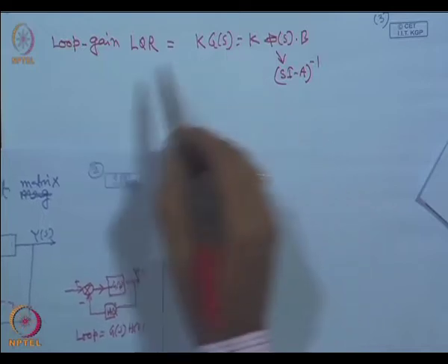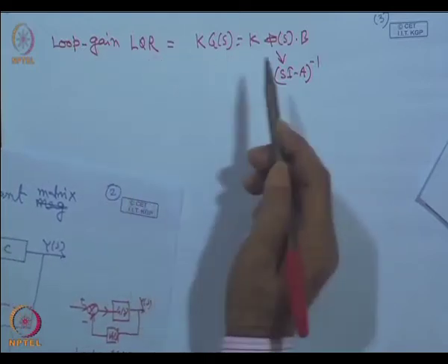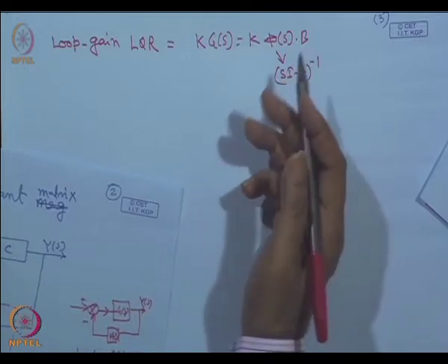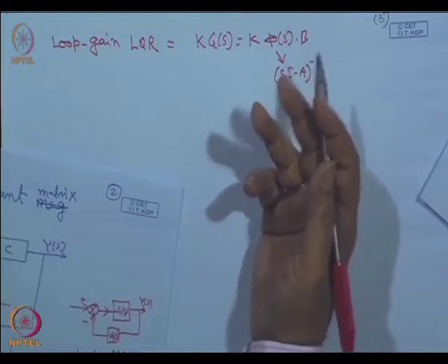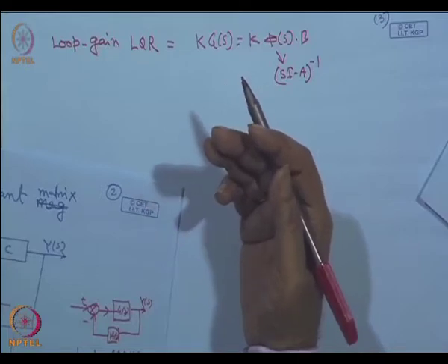And we have seen in the LQR design, for the controller K that we designed, the gain can be varied from K greater than or equal to half, or you can increase the gain up to infinity from the present value of gain, whereas the phase margin will be at least 60 degrees for the design gain K of the closed loop system.